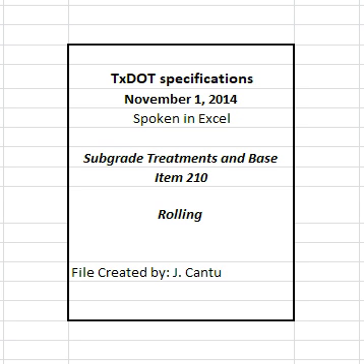Furnish rollers capable of providing a total load of 5 to 13 tons and capable of being operated in a forward or backward motion. 2.6 Alternate equipment. The contractor may use alternate compaction equipment that produces results equivalent to the specified equipment as approved. Discontinue the use of the alternate equipment and furnish the specified equipment if the desired results are not achieved.